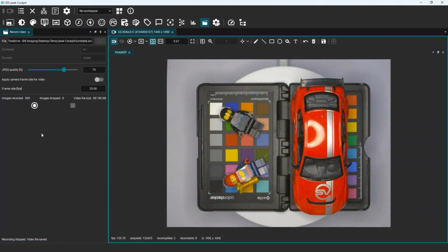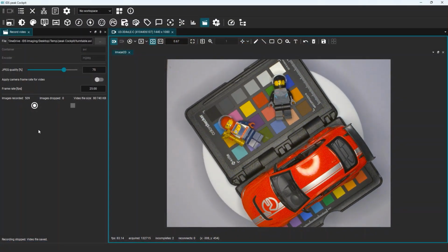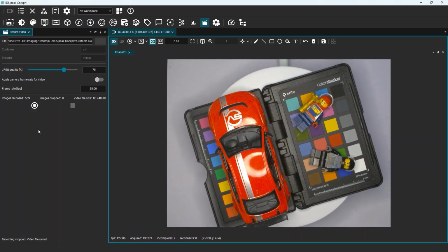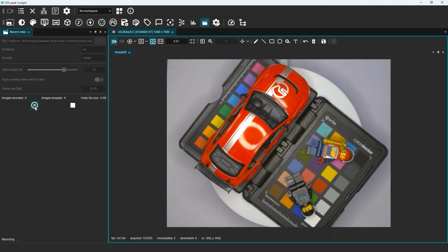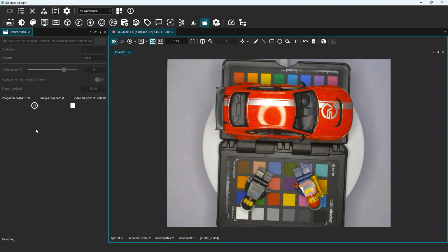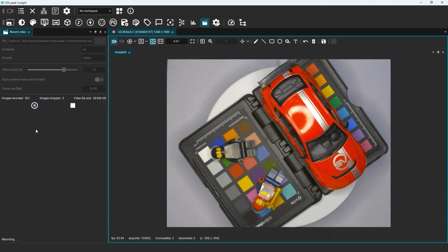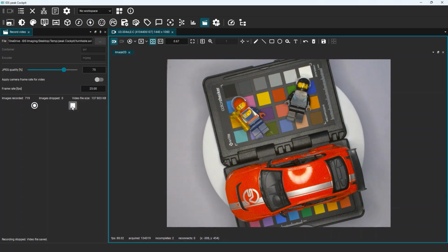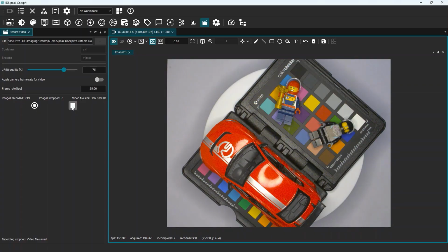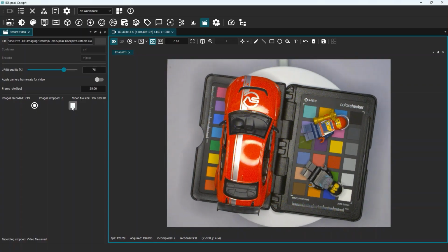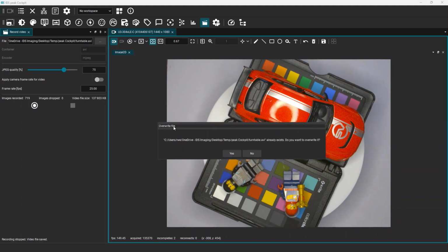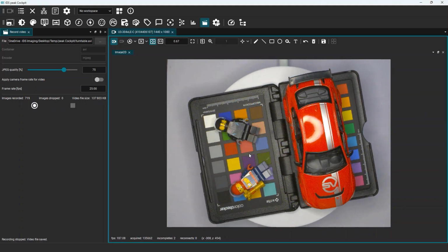As with the image saving, the frame rate can be controlled by setting the frame rate on the camera or by using a software or hardware trigger. Once configured, we can start the recording. During the recording, we can see the number of images recorded, any dropped frames, and the current file size. To avoid overwriting the previous file, if we start the recording again without providing a new file name, we see a prompt asking if we want to overwrite that file.